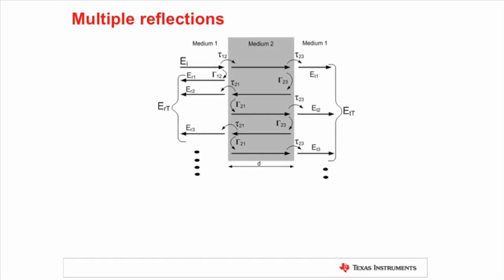These coefficients are related to gain, output power, linearity, and return loss. Any ripples in these coefficients will appear in the device performance parameters. Thus, we will see ripple formation in these coefficients due to multiple reflections. Let's consider a multiple reflections scenario with multiple reflections at the boundaries of mismatch, that is from medium 1 to medium 2 and from medium 2 to medium 1.